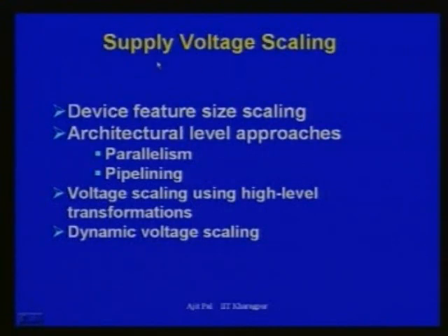Now, I shall discuss several design techniques that can be used for lowering the power dissipation. As I told, the first one is voltage scaling. Supply voltage scaling is one of the most dominant techniques used for reducing the power dissipation. So, there are several techniques using supply voltage scaling.